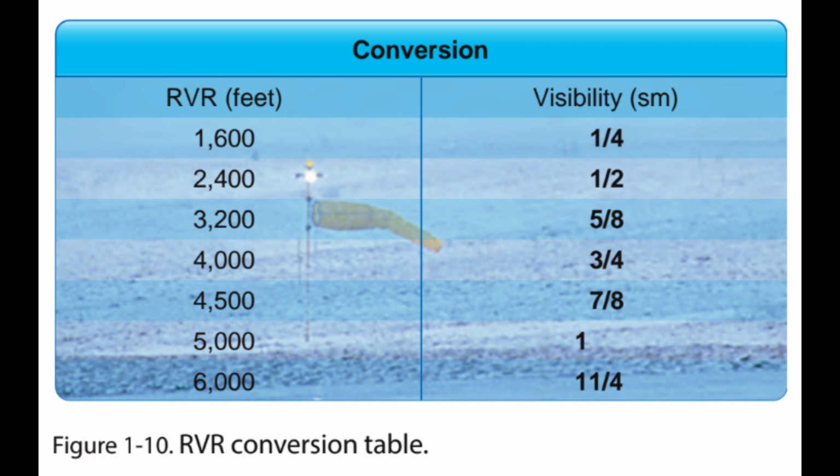Adequate visual reference. Another set of lower than standard takeoff minimums is available to Part 121 and Part 135 operations as outlined in their respective OPSpecs document. When certain types of visibility reports are unavailable or specific equipment is out of service, the flight can still depart the airport if the pilot can maintain adequate visual reference.